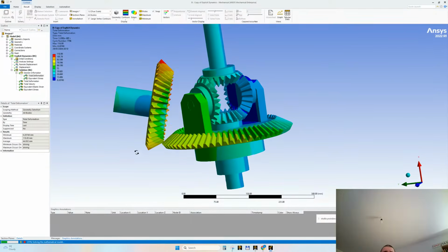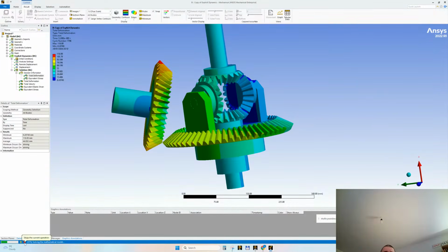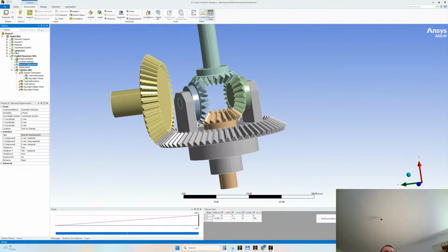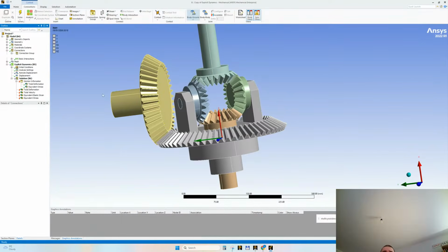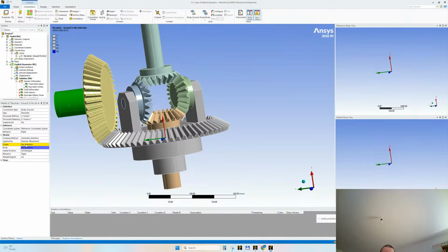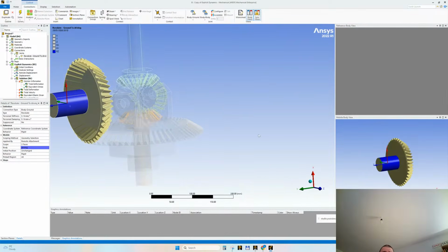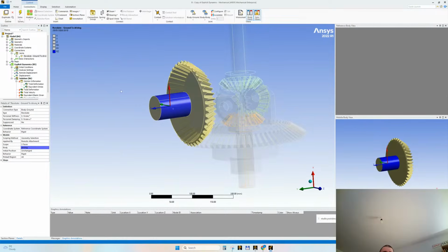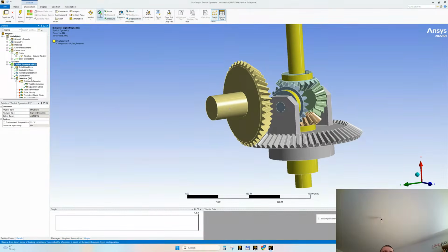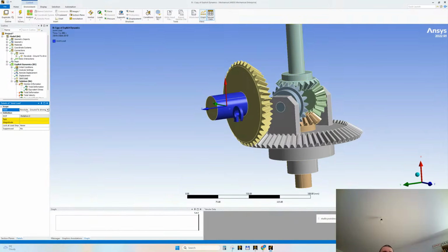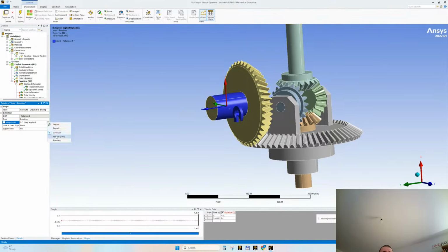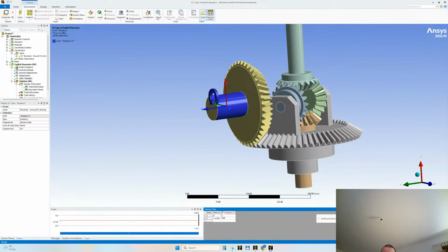I think I am forced to apply at least a Revolute joint. Please bear with me. Body ground Revolute. So it's rotating about the local z-axis here. And here we're going for joint load, rotation, and tabular time. I promised 180 degrees.